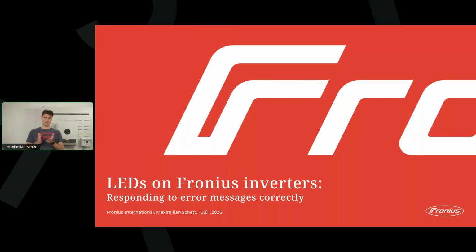For those of you who have installed some devices of our Snap Inverter series, you will remember that we once had a display on our inverters on the outside cover. With our modern inverters, the Gen 24, the Verto, the Tauro, also the Ageno, we have no displays anymore, and communication is basically just possible over Solar Web and over Solar Start. However, the only communication that remains are the LED lights in the front. The left LED light is the operational one, and the right LED light is for internet connection.